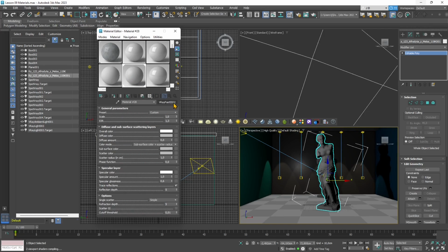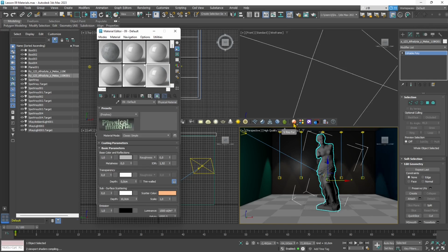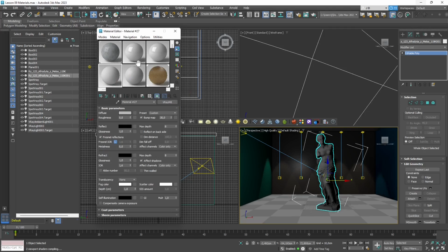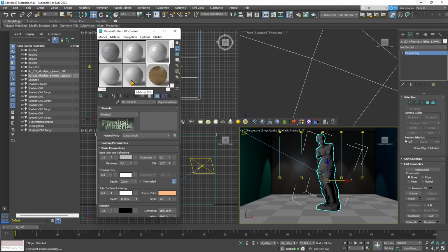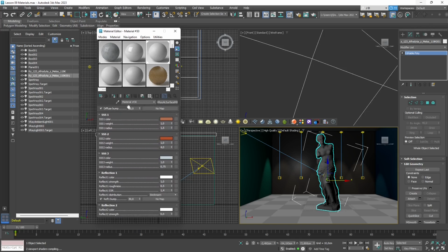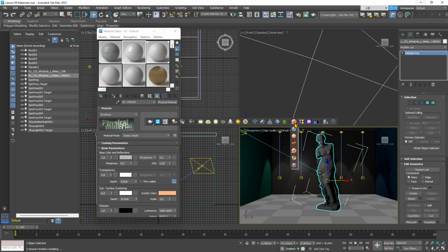But you do also have more types of V-Ray material. If you go there and on the toolbar, you can see you have hair material, which are good for hairs, and other types which are dedicated to something in particular, like subsurface scattering, or well, other really specific types that you can see, but they all work the same. They do have the parameters there in the bottom part. Now in this case, subsurface scattering is a translucent material, but we're gonna get to that later.